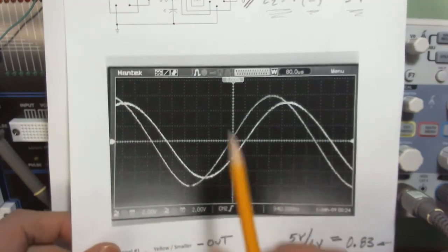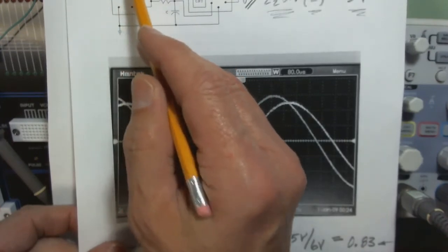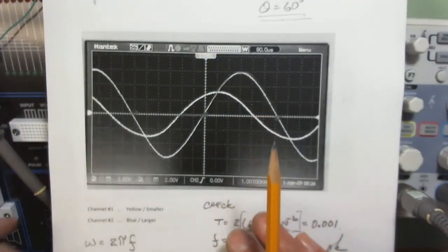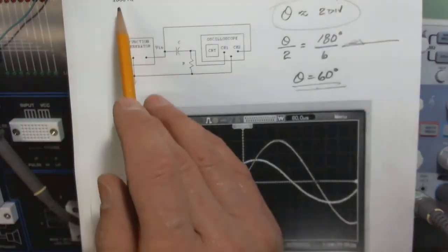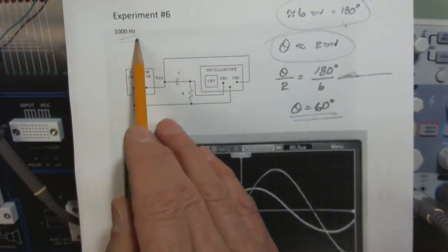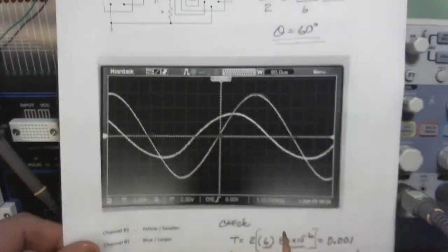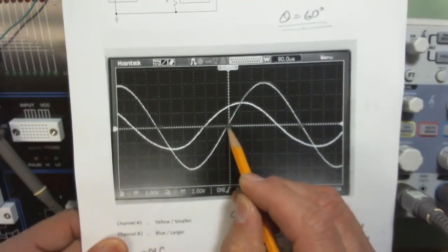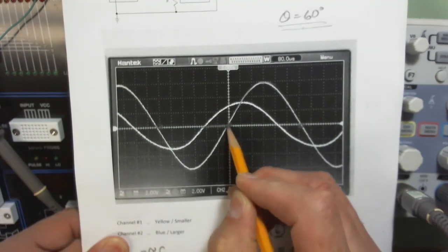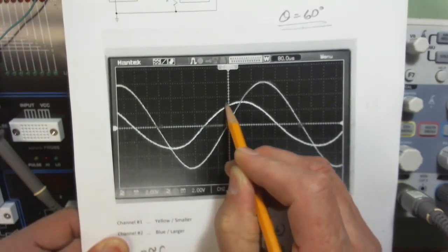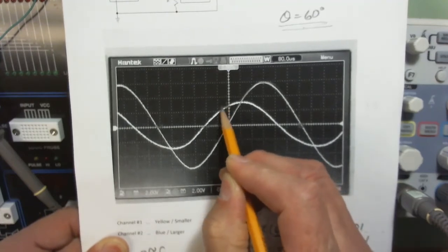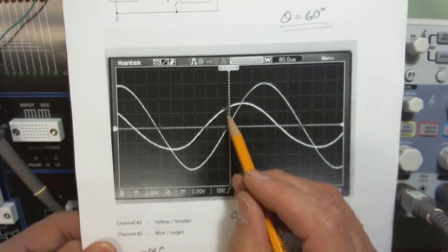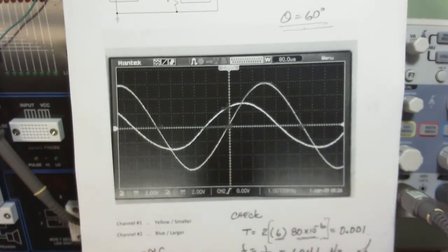And then I'm going to look at the same frequency, but when we switch those two. So that should be this one. Same frequency, but when we switch these two, I'm going to look at the input where it's 0 and increasing, and I'm going to go up here and see what value this is. It takes on a value of what? About 1 1/4 or 1 1/3 divisions.